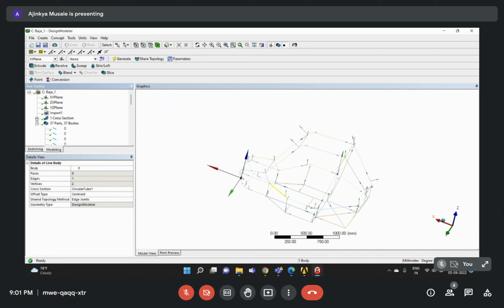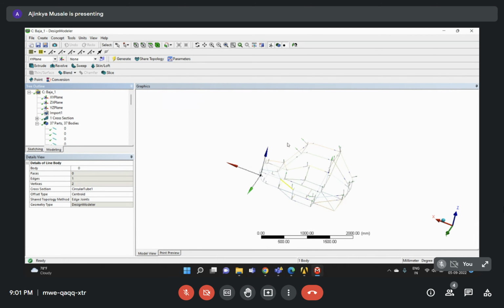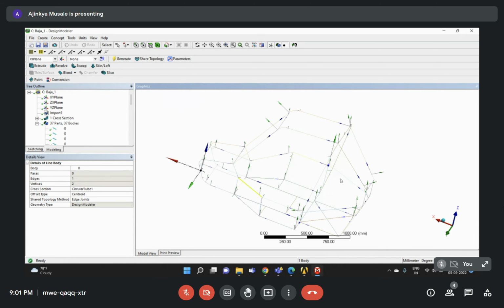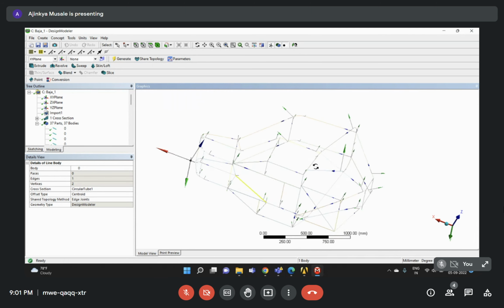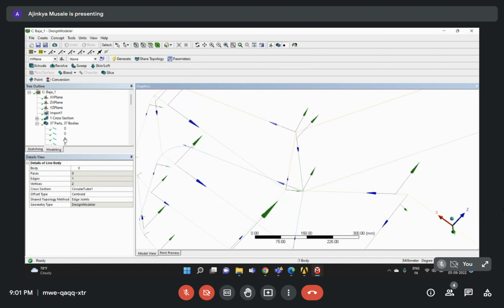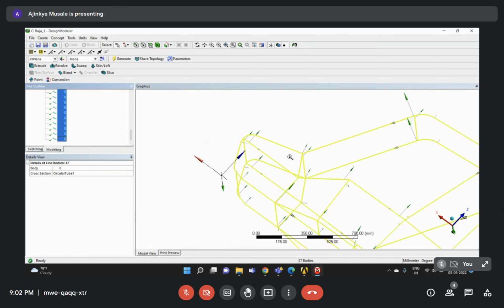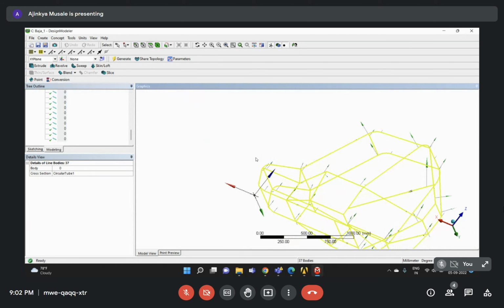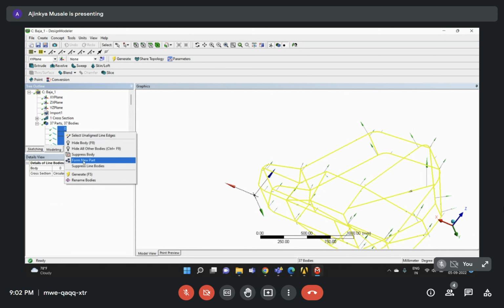Now, the very important thing. All I'm having here is 37 parts and 37 bodies. So for ANSYS, it basically has 37 different bodies. But for me, I'm seeing these bodies connected at some portion, but ANSYS doesn't know this. So to let ANSYS know that this is a single body, or these junctions are welded at this location, we just right click and say form a new part.